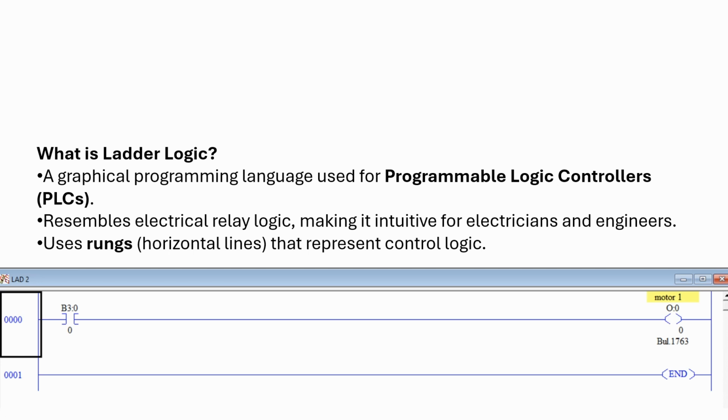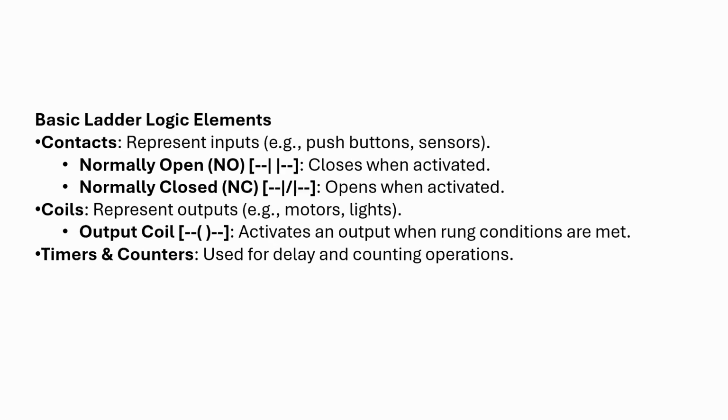And so this really got started because in the olden days they used to use a lot of relay logic, hardwired relay logic, and so a lot of your drawings looked a lot like this. So it was kind of a natural progression to use ladder logic programming in the first PLCs, and I would say it's still probably the most popular version of programming.